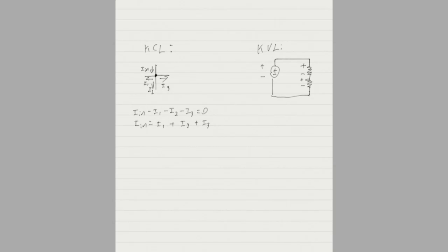So these also have plus minuses. Some people say that you should organize your circuit like this and then just do everything top down. That's one way to look at it, but the better way to think of it is, current is moving through this circuit like so. If something's dissipating power, then its plus and minus are opposed to the flow. Whereas if something's inserting power, its plus and minus are in line with the flow. So see like this. This voltage source in green, encircled in green, is adding power. These two are dissipating power.